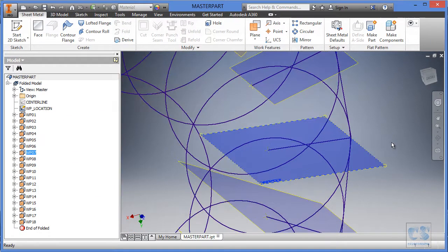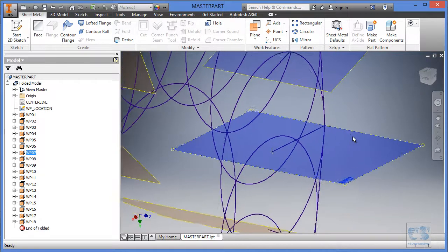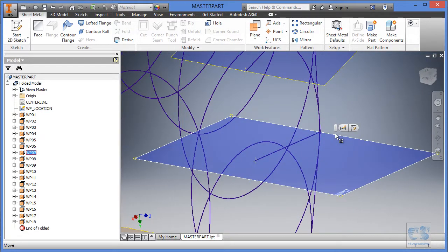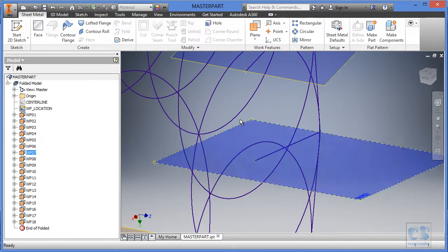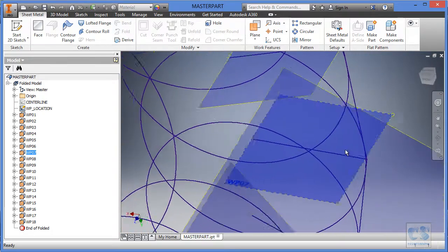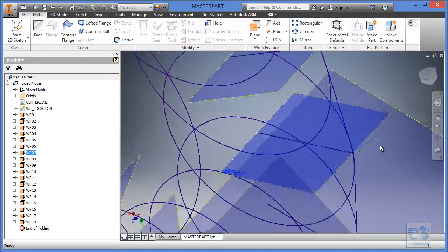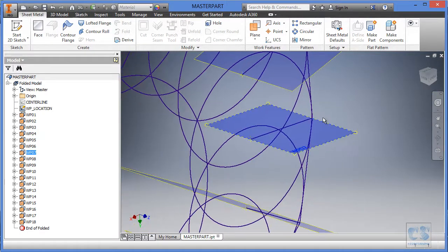So how does it improve the workflow? Well, the first thing I did later is I move one side to the correct location. So from this to this should be half of the length of the plane I want. So now I will grab this end corner and resize it to somewhere like this, and now I have the plane positioned and at the size I want.